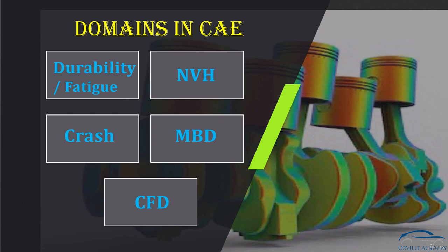Not only that, if you are in a hurry or you are angry, then you might smash the door closed. In those cases, we will be applying more force as compared to our regular operating force. This type of loading is known as abuse loading. All these loading conditions will be simulated under durability and fatigue. I hope you got a little bit of an idea about durability and fatigue.